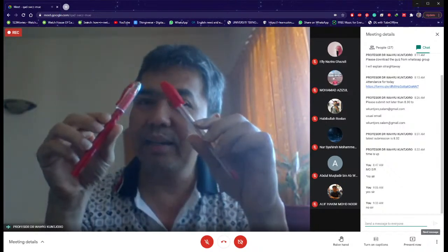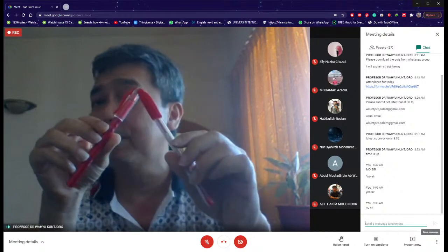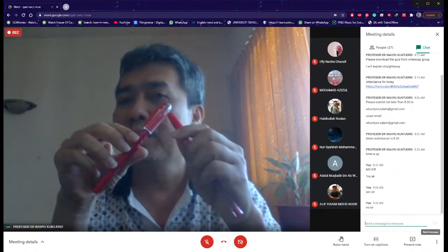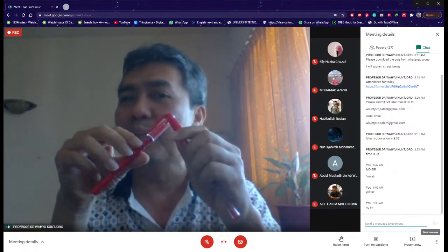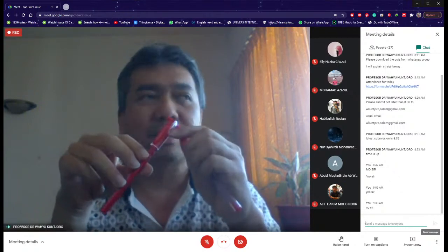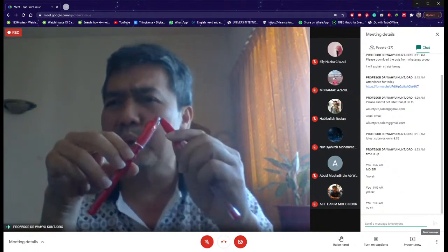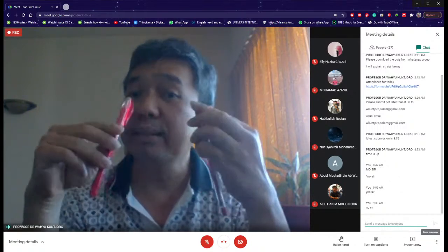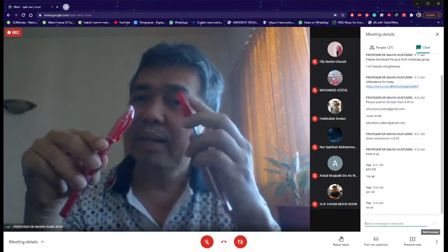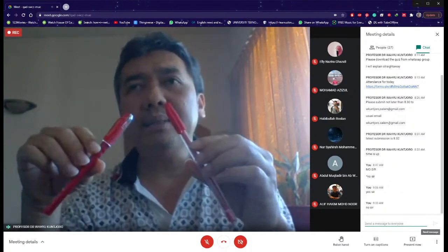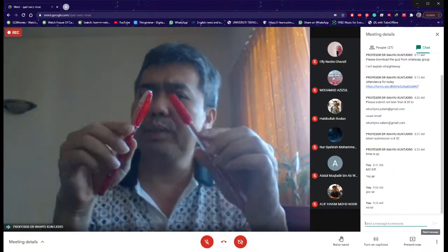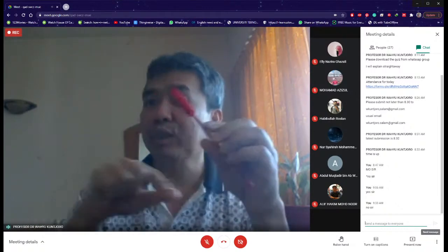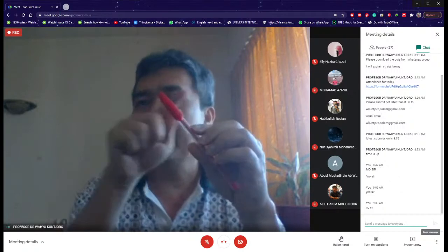And if there is no moment, you will have only what? You will have only force in X and Y. So if you are in doubt, you can open again your book, Meriam or Johnson, whatever book on statics, then you will find that, yeah, there is no moment. And that is truss. At the joint, you will have X and Y direction because it is two-dimensional, Fx, Fy.